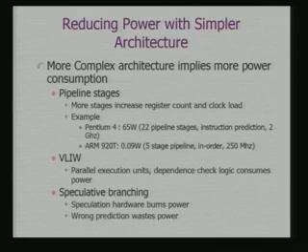Also it operates at a much higher frequency, and that is why the power consumption is of the order of 65 watts. You find on ARM, it does not use prediction, although it uses pipelining. It is in-order execution, so that prediction logic is not there at all. In fact, you will not find prediction logic in any of these processors which are targeted for embedded systems. And one of the basic reasons for this is the power consumption issue.